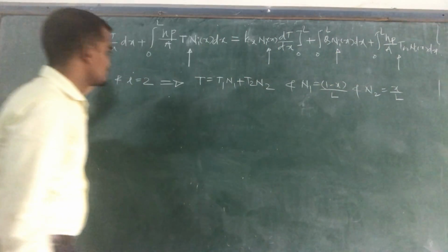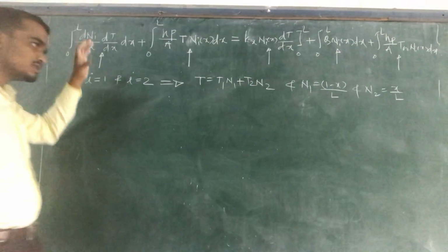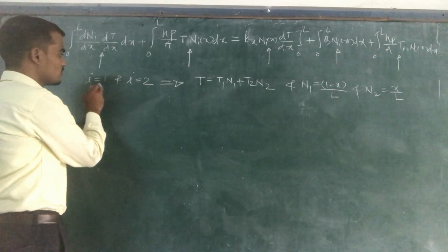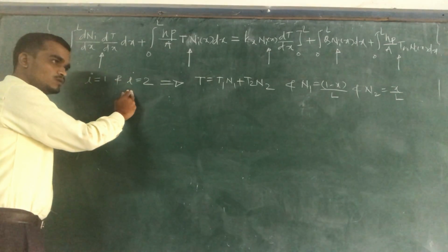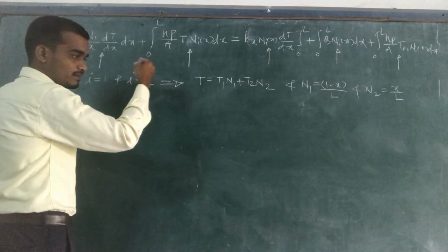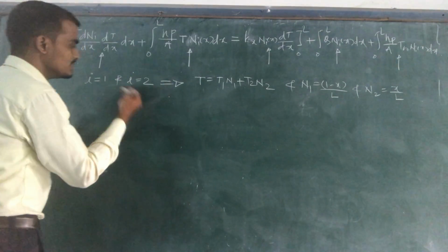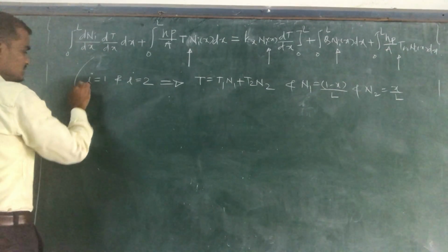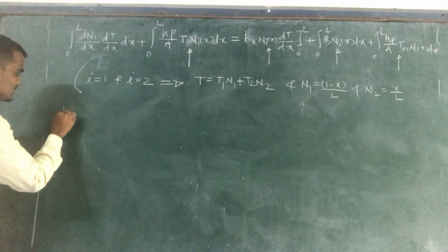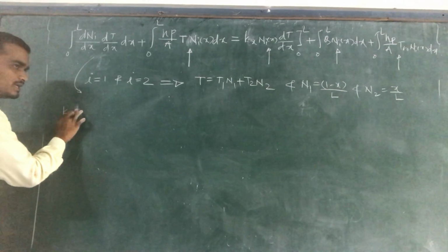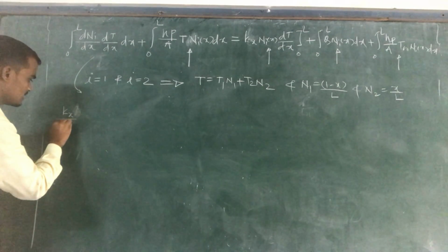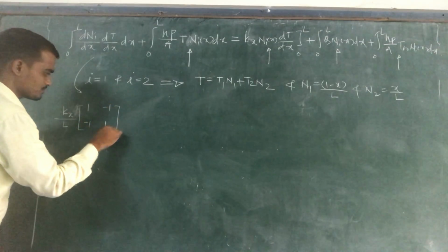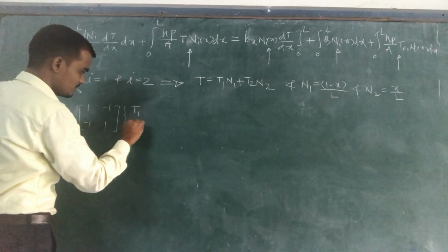Okay, so you will get 5 terms in one equation, and by solving this one equation for 2 times, for node I is equal to 1 and for node I is equal to 2, you will get 2 equations, and by writing these 2 equations in matrix form, finally you will get from this first term the conductive stiffness matrix as Kx into, now A is actually we have replaced Kx by L in bracket 1 minus 1 minus 1 1 into T1 T2